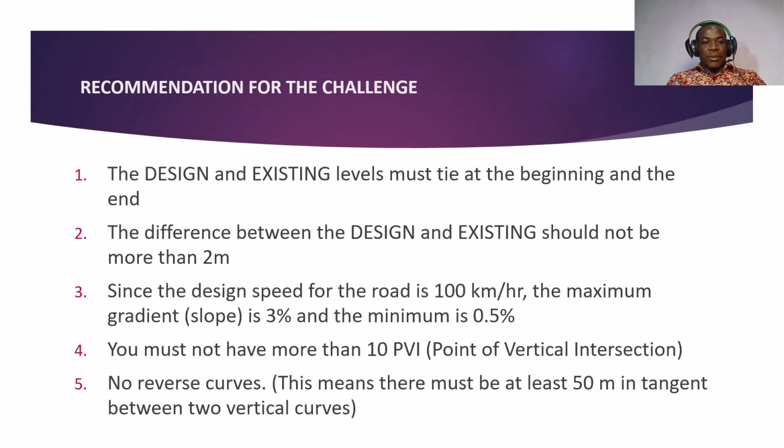So these were the recommendations I gave for that challenge. I said that the design and the existing must tie at the beginning and the end. This is a personal recommendation, and it happens sometimes, especially when the road is linking to an existing road, so you don't want to make the beginning higher. Also, the difference between the design and the existing should not be more than 2 meters. That is the cut and fill.